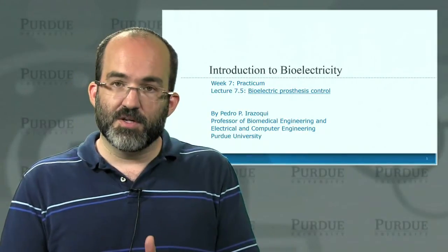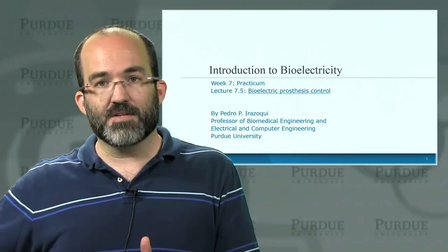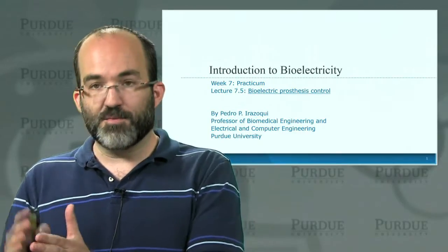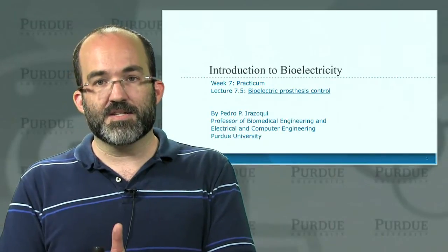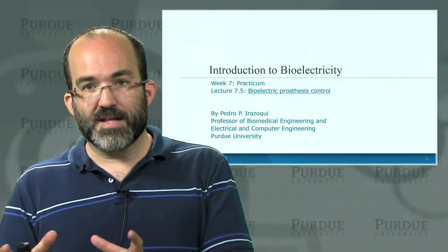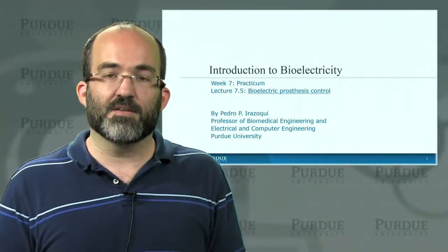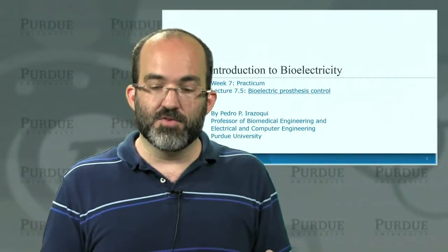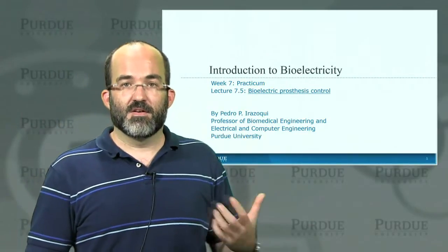In 7.2, you took the amplified signal and filtered it to get rid of the low frequency and the high frequency noise with the bandpass filter. In 7.3, you digitized that data. In 7.4, you took that digitized data and added that circuit onto the Raspberry Pi, streamed it out wirelessly, received it wirelessly with your laptop, and you are now using your laptop to wirelessly record EMG signals from the body.